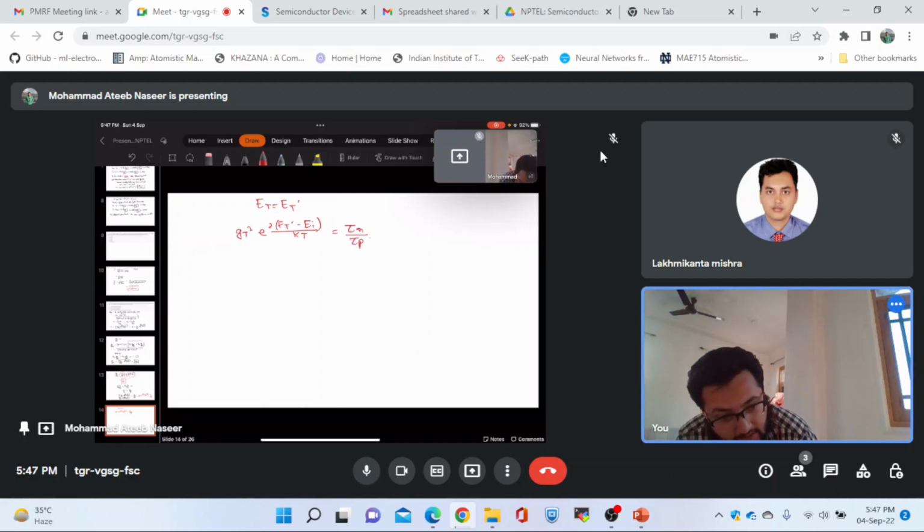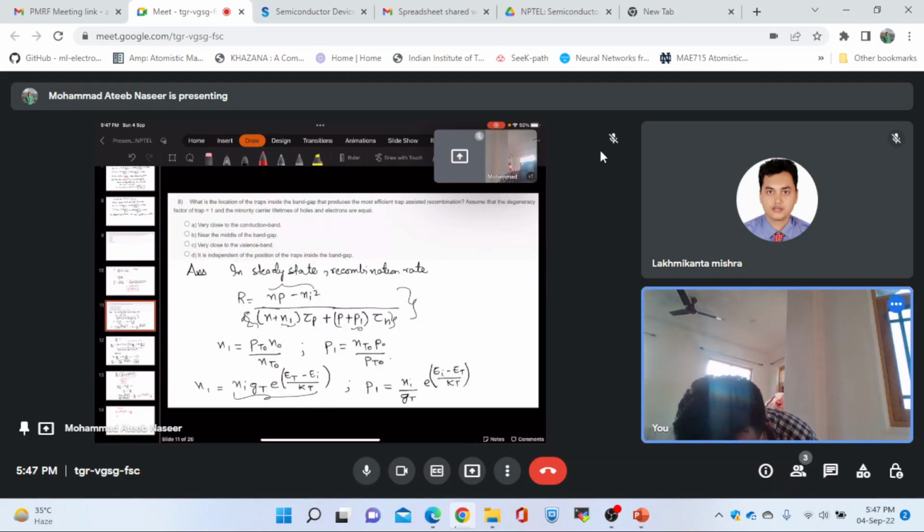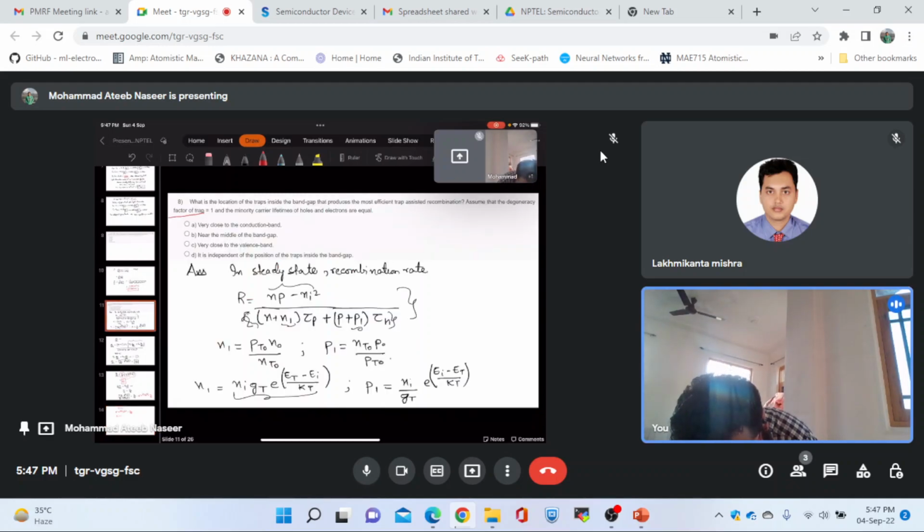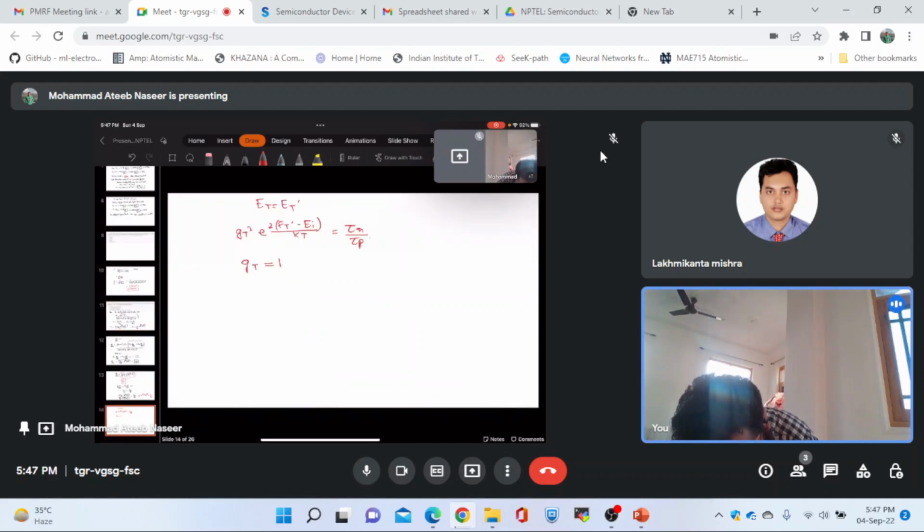But let's remember one thing that we had obtained. We had been given that this gt is equal to 1, because we have been told to assume the degeneracy rate to be equal to 1. So the gt is equal to 1, and also there was another condition stating that the minority carrier lifetimes are equal. So this and this will also cancel, and this will become just 1. So we will simply be having this equal to,